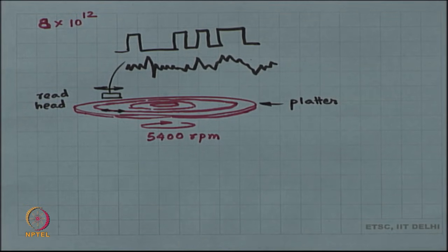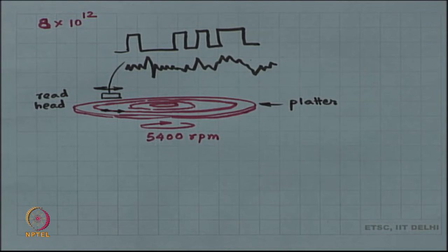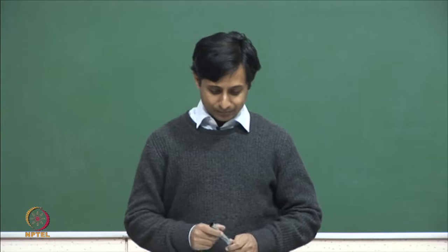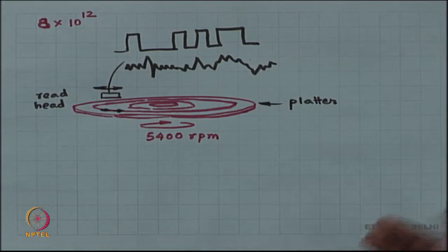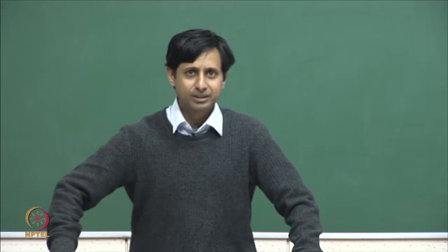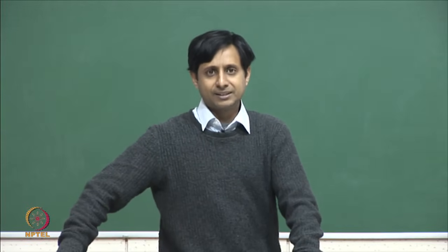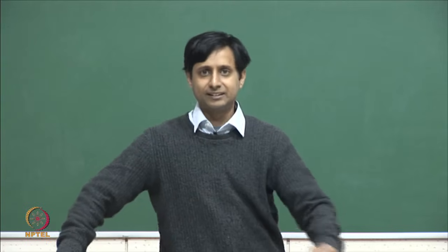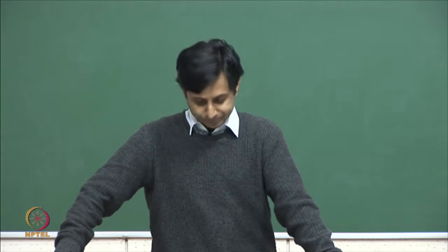Each bit is actually interfering with the next bit. So, when you think you are reading one bit, you are not really reading one bit, you are reading many bits at the same time. Each voltage sample is the effect of many different bits. It is not something very straightforward, and digitizing this signal makes no sense at all.